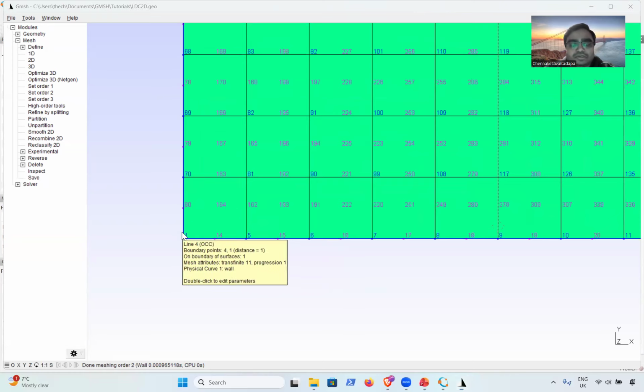Now our pressure nodes are the nodes at the element corners. So 1, 5, 6, 7, 8, and so on. And then 70, 81, 90, 99, 108, and so on. 69, 82, 91, 100, 109, and so on. So we need the nodes at the corners, not the midpoints or inside. So how can we get them? We can get them by extracting the first 4 nodes from the connectivity matrix, and then we remove the duplicates.